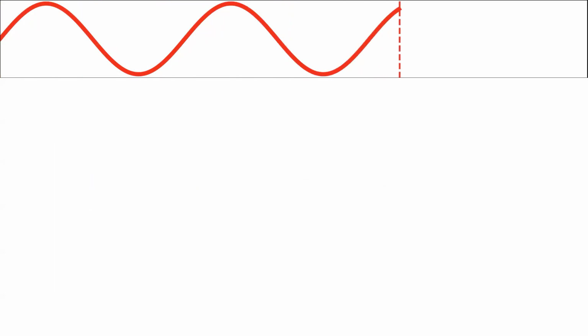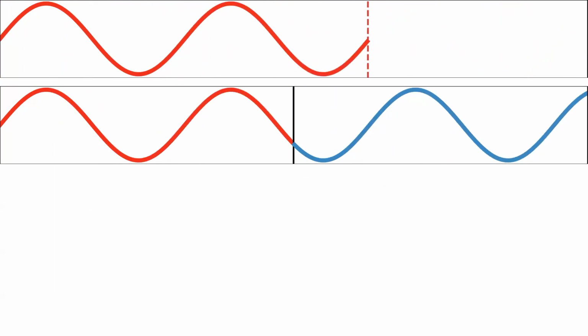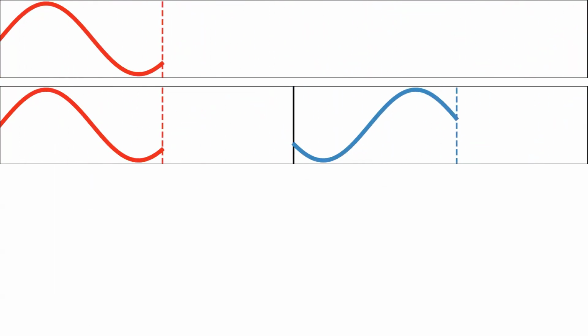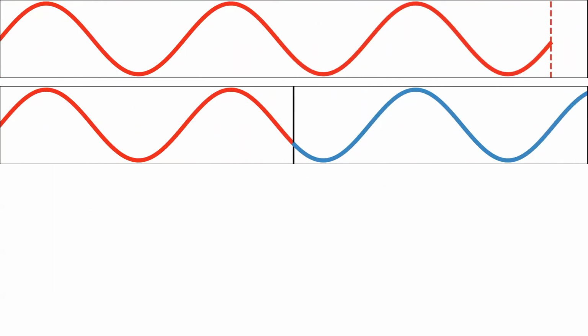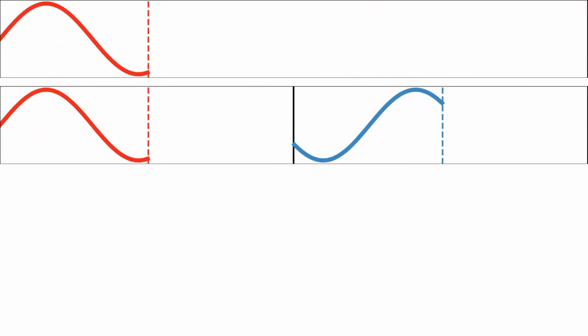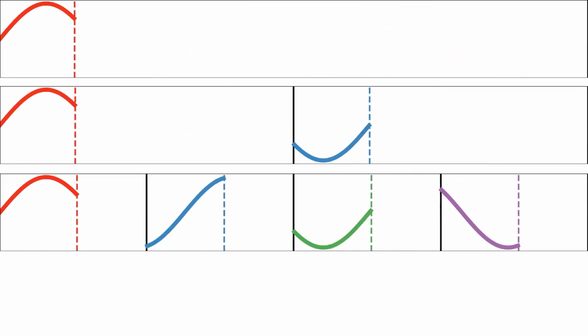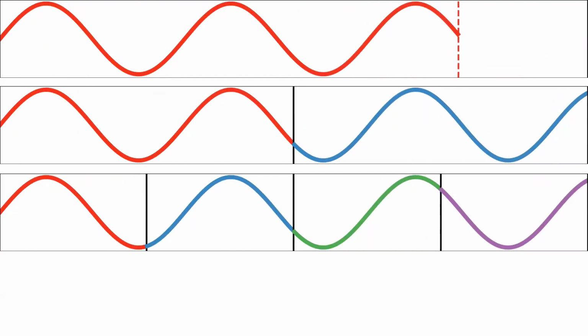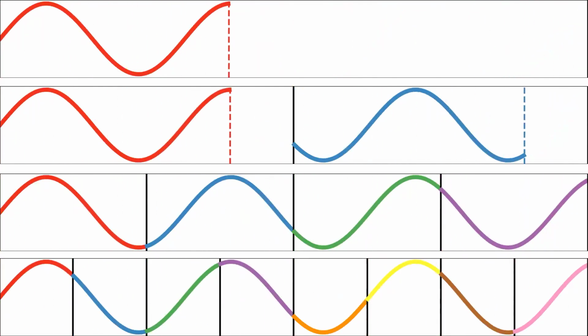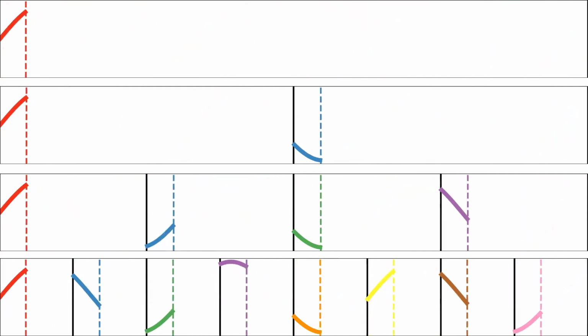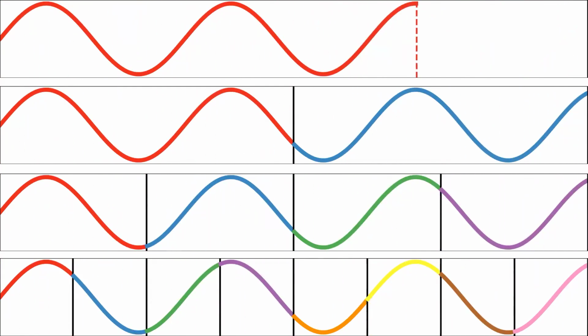So now if you look at this, why does this help when we do things on a GPU? In the first case, I'm doing just one full simulation, and say it takes 10 seconds. I can then do 2 simulations, and I can do this in a multiple shooting framework where I chunk them up into 2 windows, and then I evaluate these windows in parallel. And what I see is that the more windows we have, the more speed we have. Now I do this for 4, and the time it takes for me to evaluate my dynamics constraints is a quarter of the time of doing the full rollout. And I can keep playing this game, increasing the number of knot points or windows in our trajectory, and I can speed up the constraint evaluations.